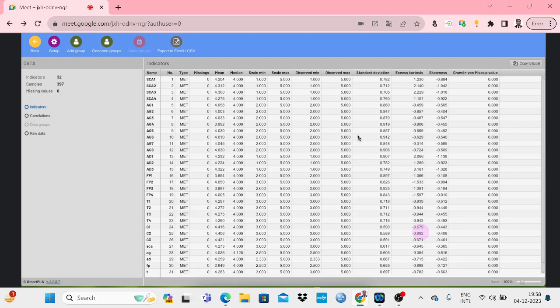This is how we diagnose problems in the data import window. When you import the data, it is not just for verifying that the data is read correctly, but also for diagnosing problems very early on. If skewness, kurtosis or standard deviation go beyond acceptable limits, then some assumption has been violated, and this will cause problems later in the model.